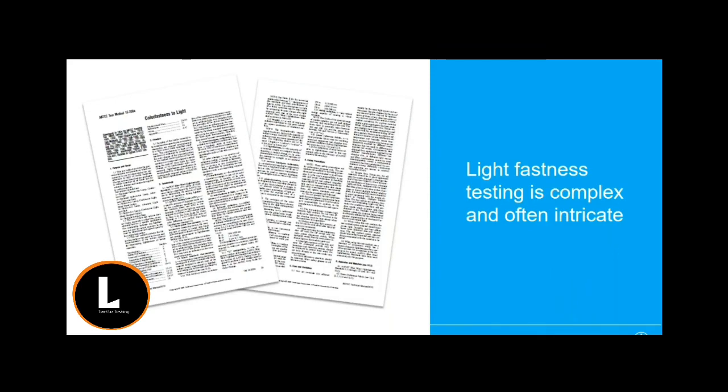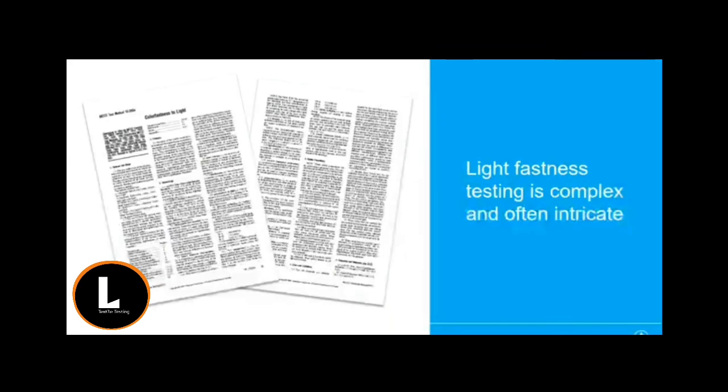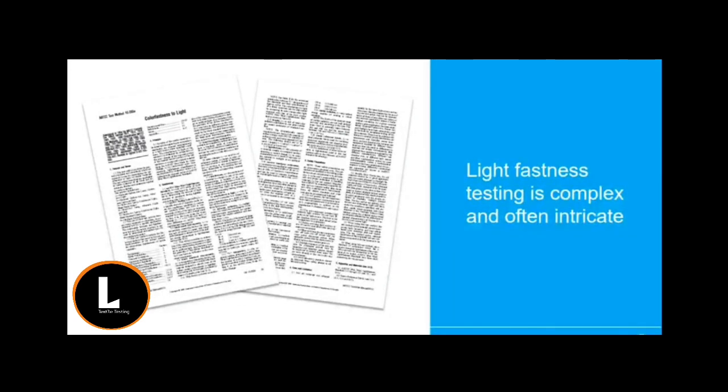So we've covered one method of one standard, and there are already many steps and a lot of detail. And this is the case for light fastness testing, which is in general quite a tricky topic to navigate. So our recommendation, as always, is to ensure that you read the standard, and for light fastness, multiple times, so that you're completely familiar with the steps that you need to take and what grading looks like once the test is actually completed.